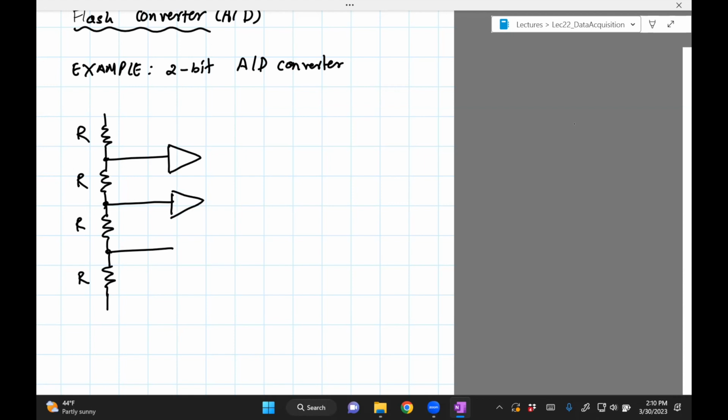We'll connect it to 3 comparators. So these are op amps. And then this is the input. So connect it here. So the dot here would represent the connection. So if you see a cross line, doesn't mean it's connected unless I show it with a dot. Correct. It can go all the way here.